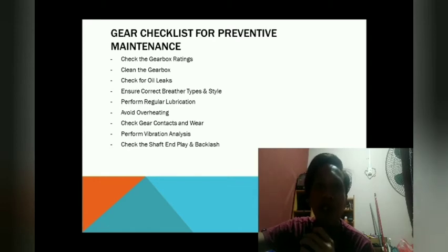Next, perform vibration analysis. Generally, gearboxes are used in noisy environments. Therefore, even if there is any chance of rise in the gearbox noise, it can go unnoticed, which is very risky. Thus, it is highly recommended to carry out vibration analysis to keep a close check on the gearbox noise and vibration.